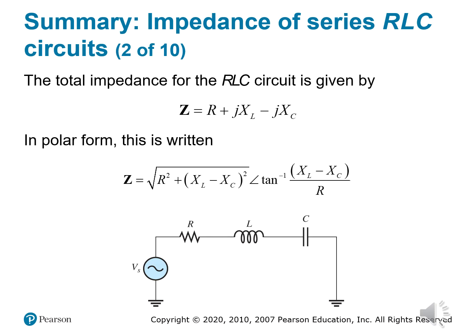So in complex form, the total impedance, Z, of a series RLC circuit is Z equals R plus j X sub L minus j X sub C. And this is saying that we've got resistance from R, inductive reactance from X sub L, and capacitive reactance from X sub C. Since the capacitor's reactance is out of phase with the inductor's, we subtract it, and that leaves us with a complex number, a real part R, and an imaginary part X sub L minus X sub C.